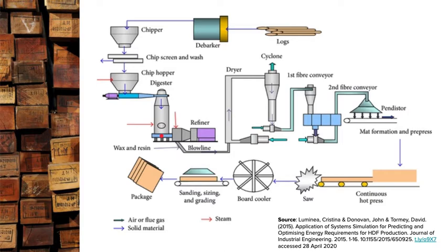The pieces or the fibers of timber are exploded. They explode under a huge amount of pressure. Okay? So they put them into a machine, they soak them in water, and then they add a whole heap of pressure, and those timber fibers basically blow apart into individual pieces, individual fibers. Once that's done, they're dried out and they're sent all the way through the machine onto the conveyor belts,